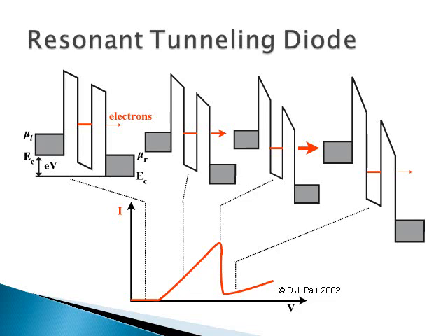When solving Schrödinger's equation between two closely spaced potential barriers, energy levels become quantized. What this means is that only electrons of specific energies are allowed to transmit in these quantum wells. The gray region in the diagrams shown are areas on the opposite sides of the RTD where electrons are, and the orange line in the quantum well shows a quantized energy level. Initially, when a small bias is applied to the junction, which is seen by a downward slope in the potential energy profile, the gray area does not align with the quantized level.